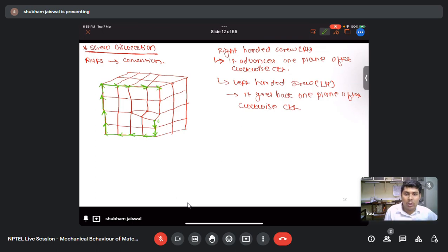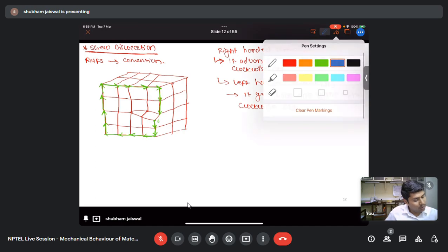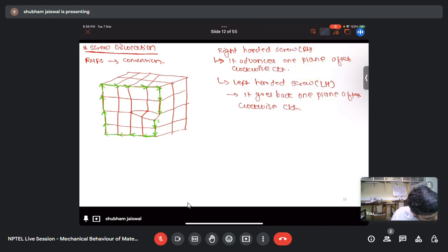Now this left movement and right movement is the same. Now I need to check the movement: here I went 4 steps upward, so now I need to move 4 steps downward. Here this is 1 and this is 2, and already we have moved 2 steps down, but these 2 points are not coinciding. So it means some dislocation is there, and this is the screw dislocation.